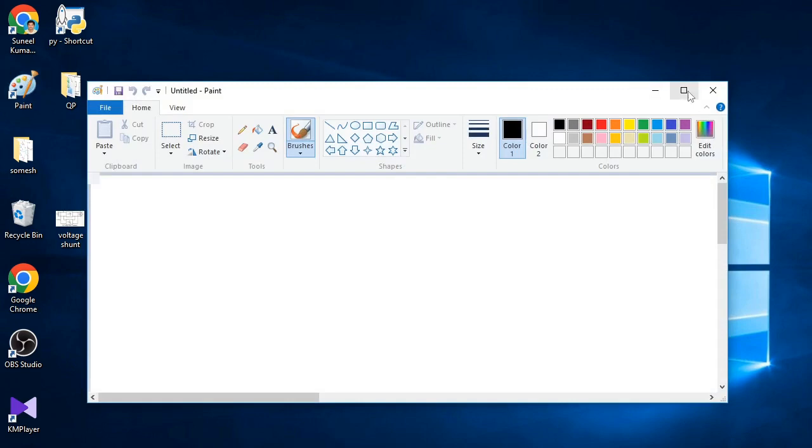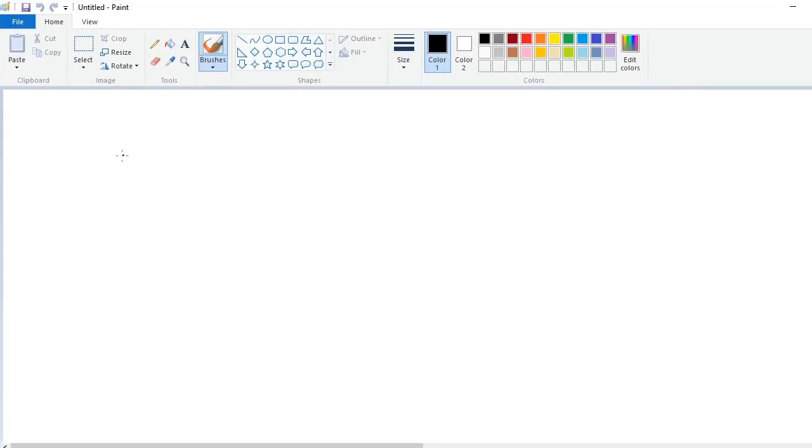Now coming to the output resistance derivation. To get output resistance, input must be equal to 0. What is the input here? Vs is equal to 0. So we know that Vi is equal to Vs minus Vf. Put Vs equal to 0, we'll get Vi is equal to minus Vf. Now again draw the output portion of the equivalent circuit.